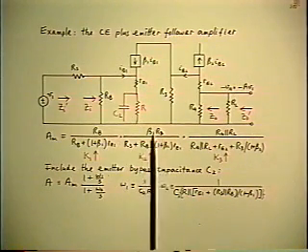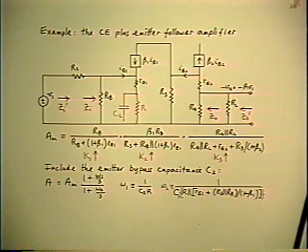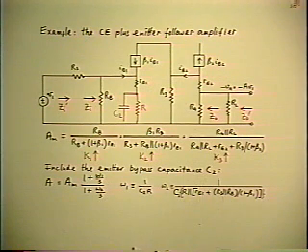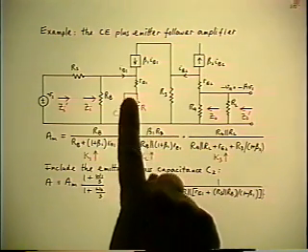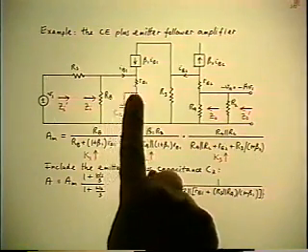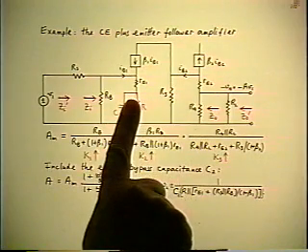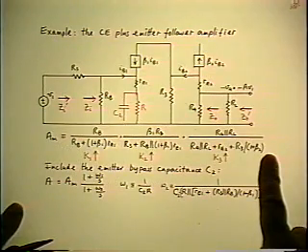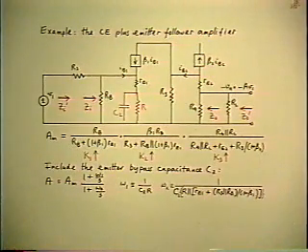Now, this time, I won't draw any intermediate diagrams or write down any intermediate equations. We'll do it all mentally, just by visualizing the intermediate steps. So, the reference condition is when the cap is a short, which kills the resistor automatically at the same time. So the reference gain is AM as we have before. So all we have to do is find the two driving point resistances.